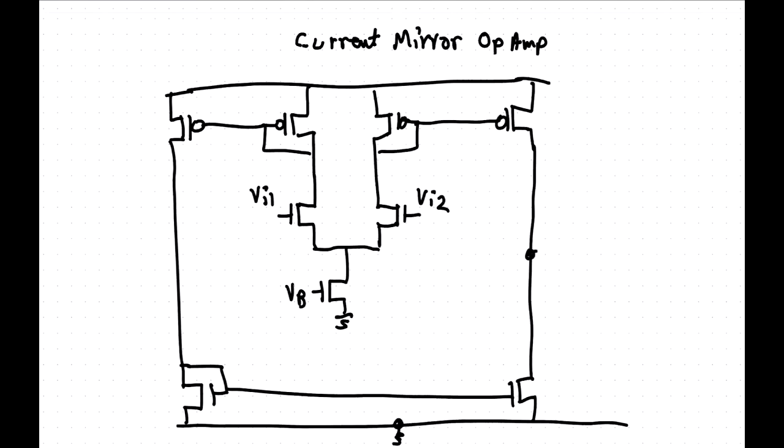The current that flows down in the right-hand branch here is going to flow out of the output. The current that flows down in this one here is going to flow all the way to the left, and that's going to flow into this transistor here. So this structure subtracts the two currents at the output node, rather than having one current mirror that sits up there.